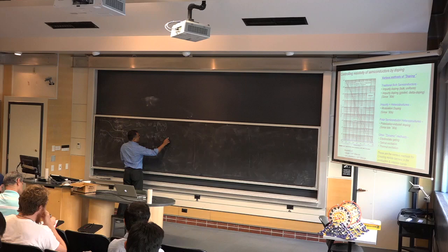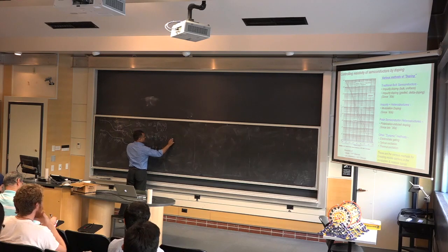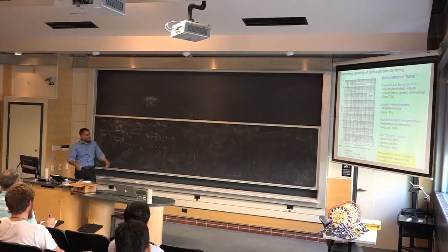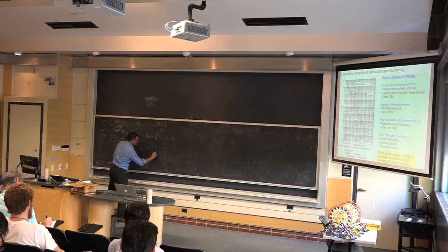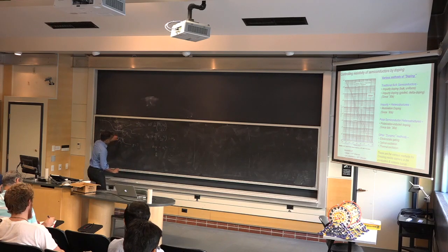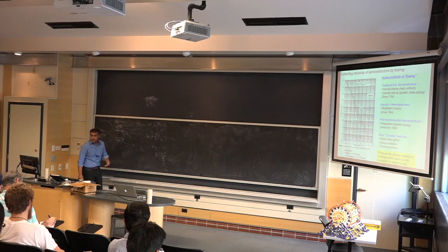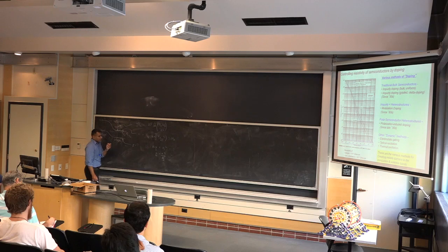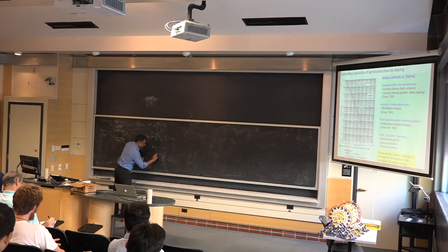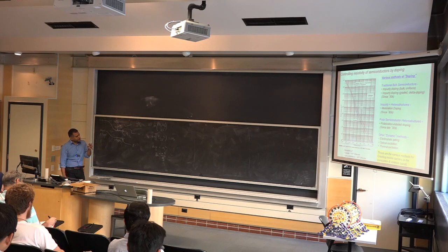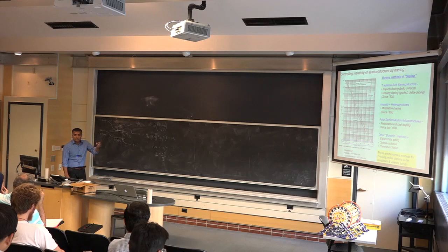Now, very far on the right side, I can say that N is roughly equal to my doping density, right? Because I've doped it, things have ionized, it's roughly that. As a result, the P, the hole density in this region, is Ni squared over the electron density, which is roughly equal to the doping density. Right? So even in an N-type semiconductor, I have a little bit of holes left. So I would rather label it, since I'm on the N side, typically with a P sub N, saying this is the number of holes in the valence band in the N region.